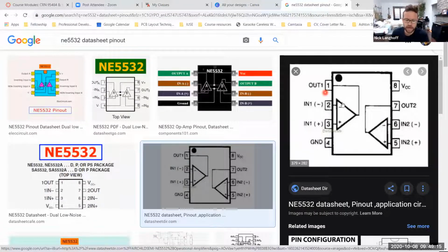So all to say, not all 8-pin packages are single op-amp packages. In fact, there are other 8-pin packages that are completely different. They're like a small microprocessor or a piece of memory or something like that. So whenever you see an 8-pin chip on a board, you can't necessarily assume it's an op amp straight away. There are certain designs where it's a safe bet, like, oh, that's probably an op amp.